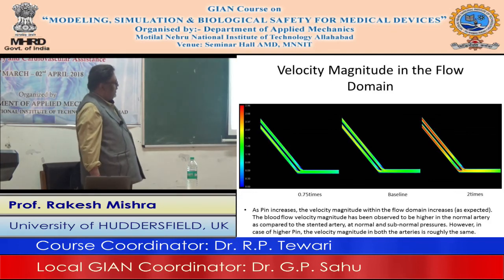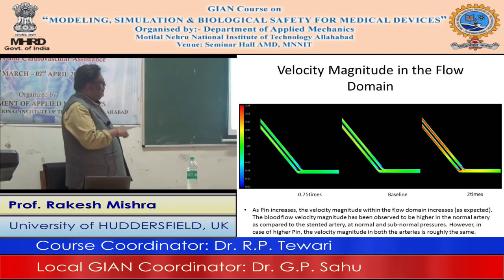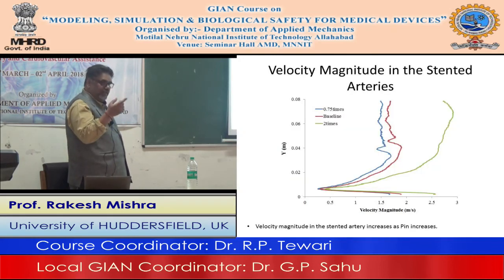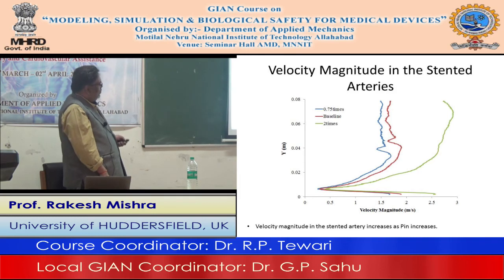This is the velocity profile. And why do we plot velocity profiles? Because the gradient of velocity at the wall gives me wall shear stress, isn't it? We did yesterday mu du over dy. That is why u is very important. So this is how u is varying along y, and you can see that although the pattern is almost similar, the velocity magnitudes are higher when there is higher P in. So we have P in here, this is along the length, this is very, very high, and these two are almost close to each other.